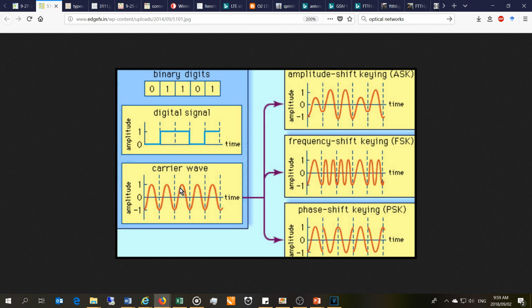The carrier wave is a much higher frequency wave. The reason why it's much higher frequency is it's easier to send higher frequency waves through the air than lower frequency for various reasons. And that has to do with distortion, noise. Now, here we have the amplitude shift keying. There we go. Another option is frequency shift keying. Can you see how the frequency of the carrier is shifted based on the binary data here, the binary signal? So when it gets demodulated, remember this is modulation, going from this to that is called modulation.